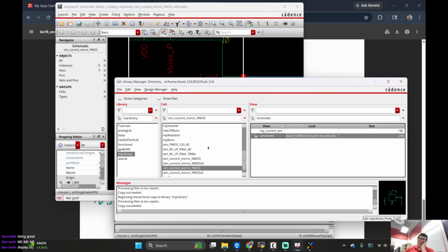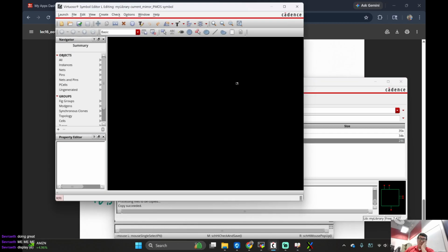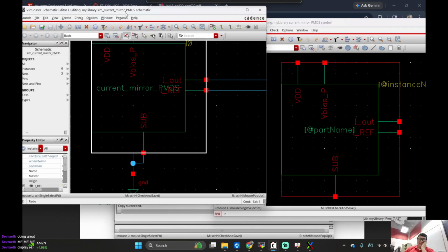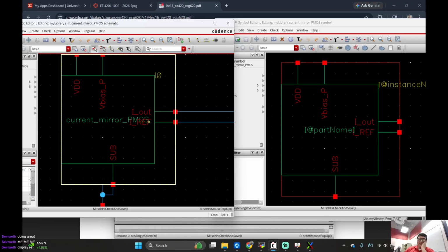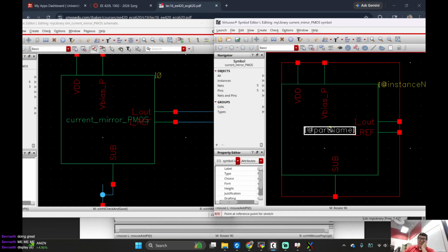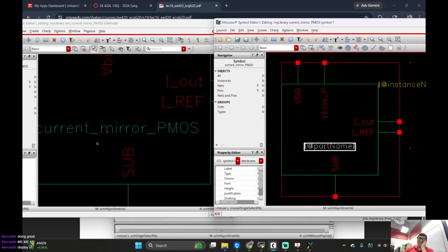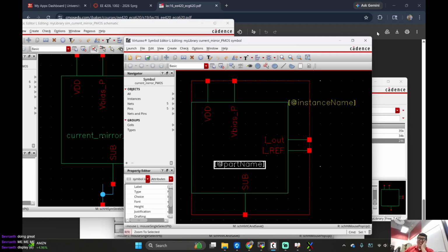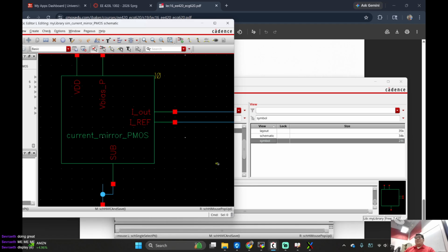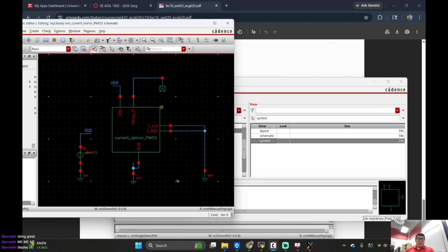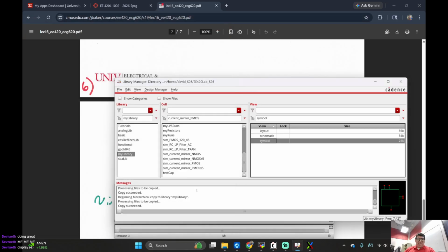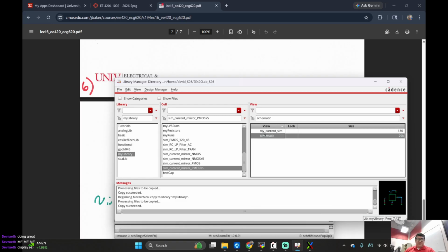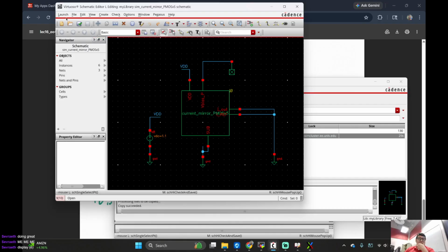For those who have OCD like me, go here, right? Go to your symbol. I'm going to show you a trick. Here's your simulation, correct? Who wants to be perfect? Press M. Push this down. See what happened there? Clean. Just to make your life easier, okay? But anyways, I don't need that one. What I needed was this guy right here. Where is it? PMOS times 5. Okay. Check and save. Launch.